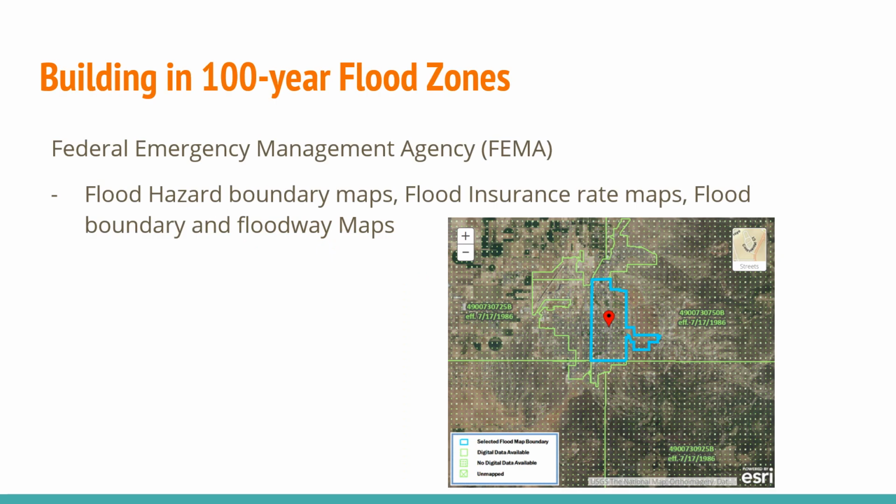So first things first, for those people who receive lots of rain, we have to prepare for 100-year flood zones, which according to FEMA are essentially zones with a 1 in 100 chance of a flood taking place. Now, obviously, it isn't just 1% per year. It's just the average of how often we see these catastrophic floods.